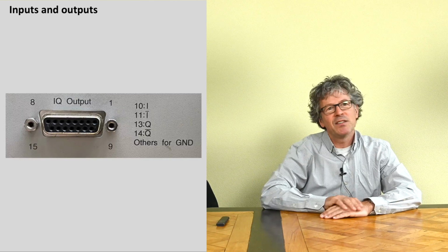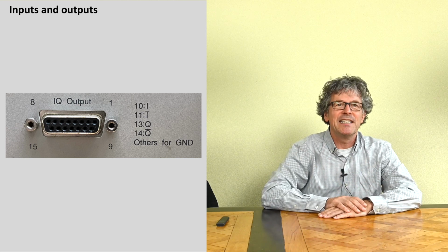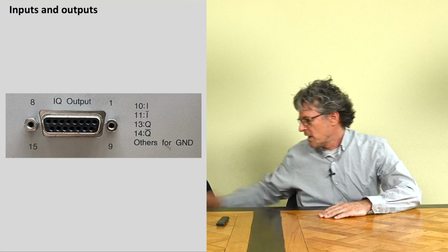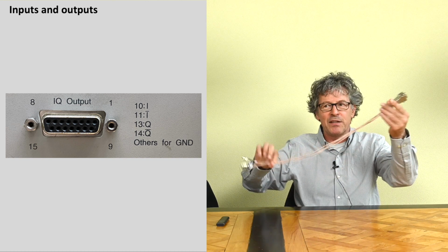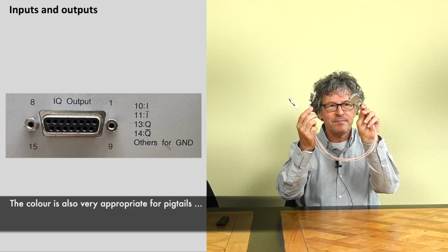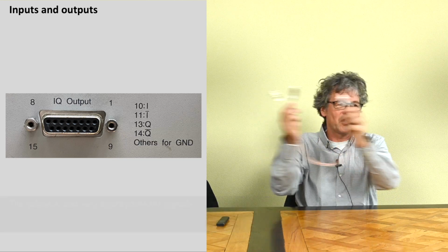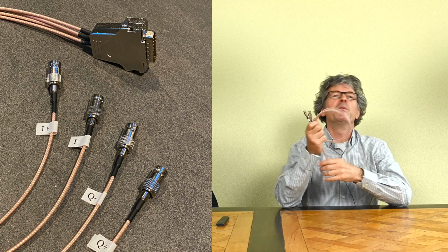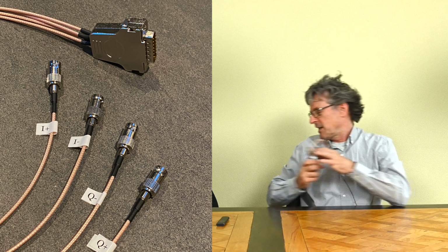But actually they're not 4 BNC connectors. That would have been really the easiest way. No, they have some 15-pin D-sub connector with the signals. It is not so much of a big deal, and I eventually made this little cable here with 4 pigtails and tried to shield it properly. I'll try to show a picture of this cable. But it's still a bit of an inconvenience. I really wish they just would have fitted 4 BNC connectors. That would be just so easy. So I don't know why this particular design choice. All the rest of the connector is unused. It's all ground lines.